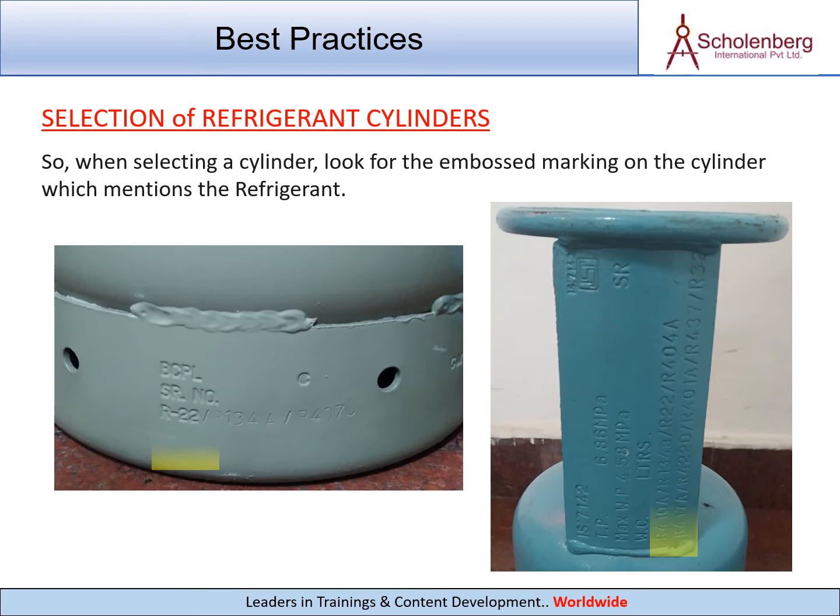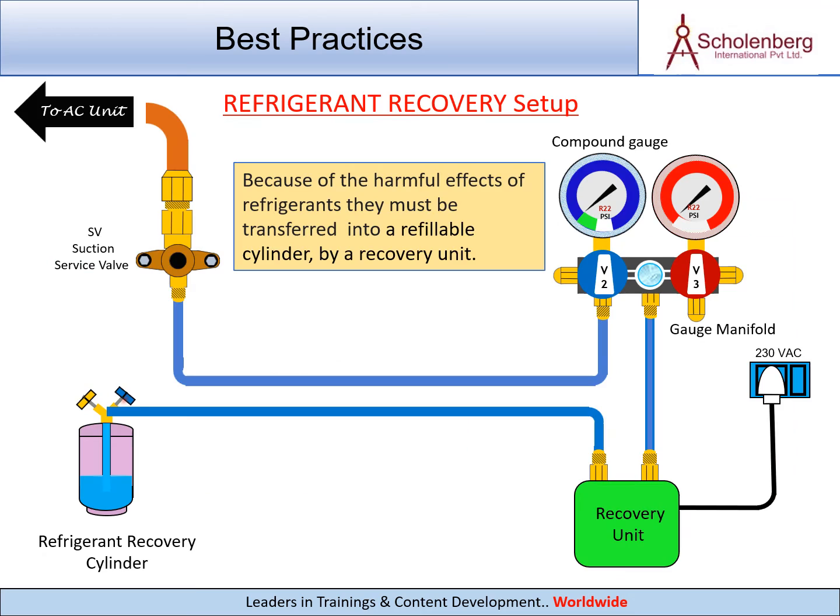So, when selecting a cylinder, look for the embossed marking on the cylinder which mentions the refrigerant. Refrigerant recovery setup. Because of the harmful effects of refrigerants, they must be transferred into a refillable cylinder by a recovery unit.